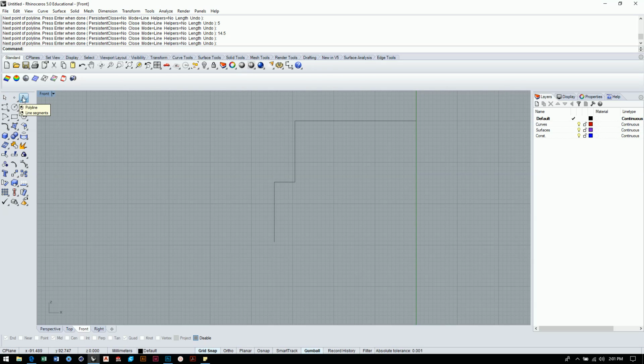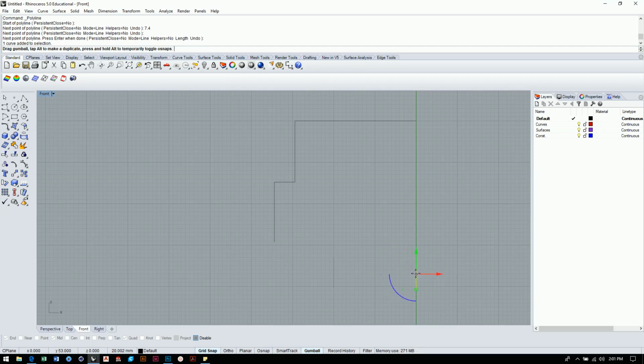And so I want to get that figured out really well, so I'm going to click just once here, and then I'm going to go 7.4, and then I'll hold this. Okay, I'm just dropping that line anywhere in space. Okay, now I'm going to move it over until it lines up with the z-axis, and it's sitting right there.